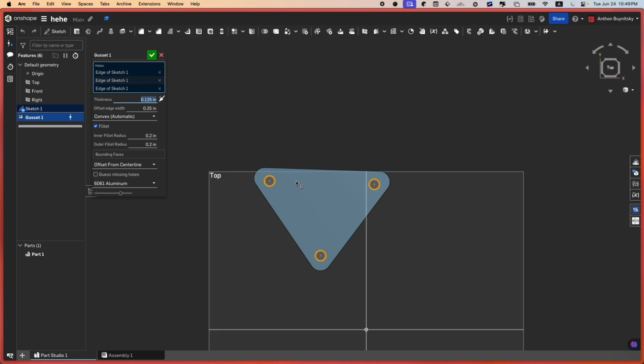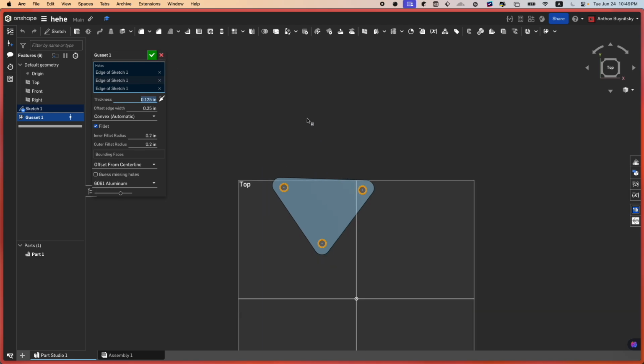And then the material you guys can cut, at least for aluminum, is 6061 aluminum, which is kind of like the general one that is used across FRC. It's generally strong. It's not as expensive as other aluminum types, and it's kind of just the standard. And then another one that you guys can use is 5052, which is a type of aluminum that is used for bending.